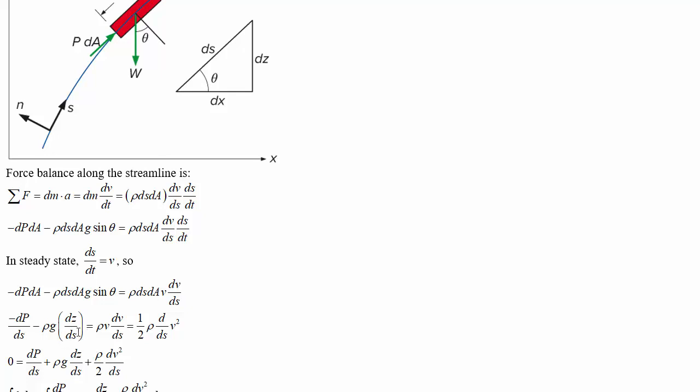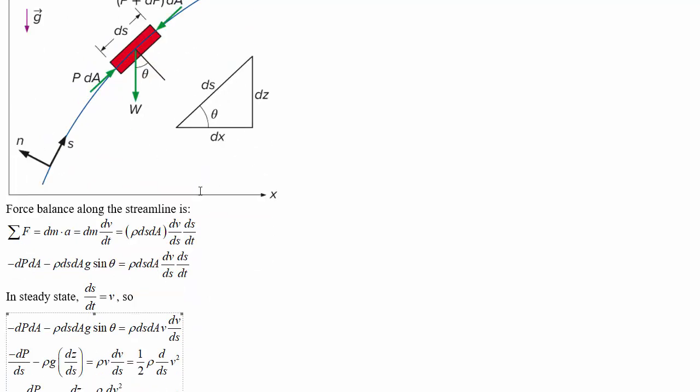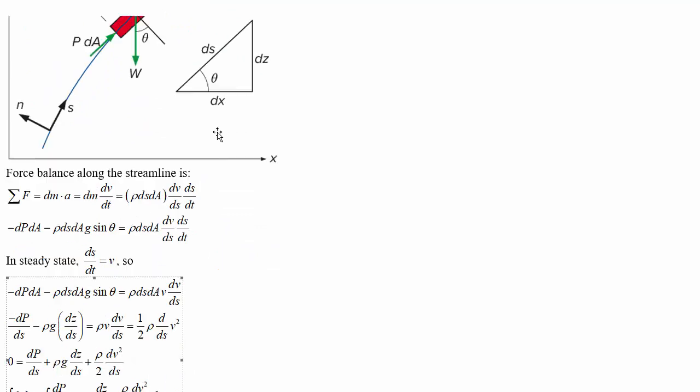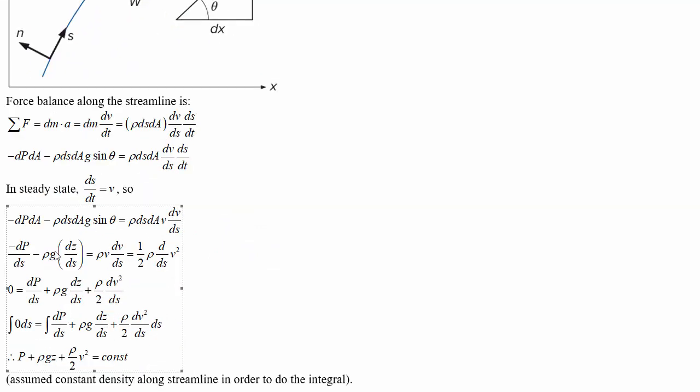Then we also divided out the ds from this term and this term to get it on the denominator over here in dp by ds. Since we had another d by ds show up from the factoring that we did from the chain rule on the right and from the sine substitution for the triangle there for sine theta, we have every term with a d by ds. After we rearrange and put everything on the right-hand side, it looks like this.